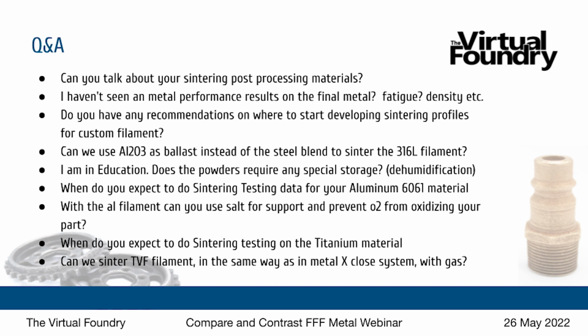When do you expect to do sintering testing data for the aluminum material? Ooh, yeah, I just got a new batch in. We're partnering with Filamet. They make aluminum powders, and we just got a batch with some additives in it. It'll likely be some type of a fluxing agent or something that can lower the melting point of the oxide layers that cover the particles in the aluminum. So there's a solution there. We'll find it. I would say nothing goes quickly. I was thinking 2 months, so we'll double it for Brad, and I'll say maybe 4 months, somewhere in there.